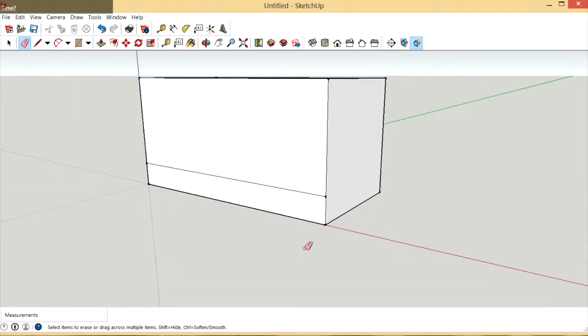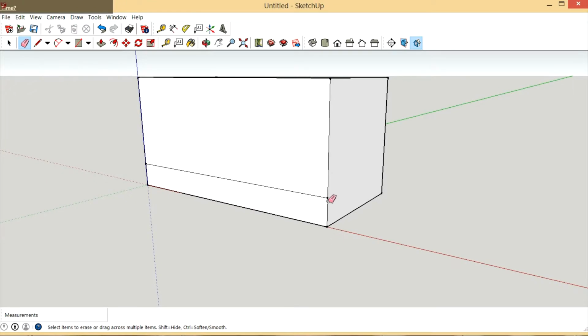construction line there. So now what I think I'll do is start as if I was building this thing. It's what I normally do when I'm designing things, and I start with my footings. So I'm just going to draw this freehanded now. You can see here that depending on the color, initially, I don't know if you can see the green there, but that means I'm on that green axis there. And since you're working in 3D, it's nice to have handy indicators like that. And you can see there it says on green axis.